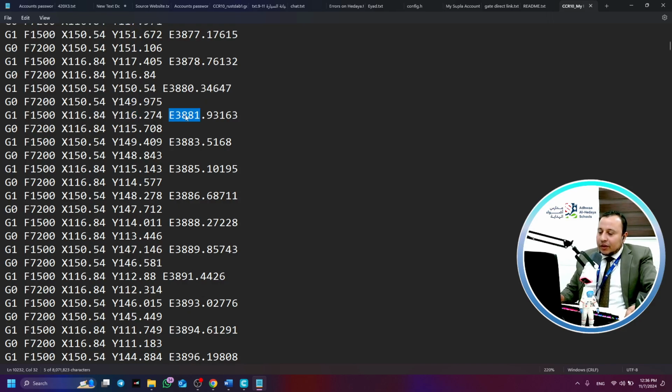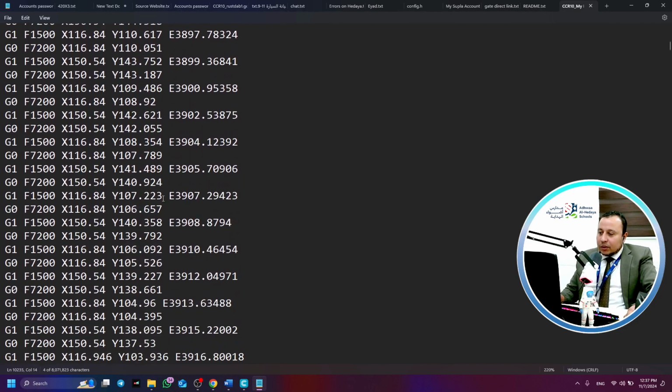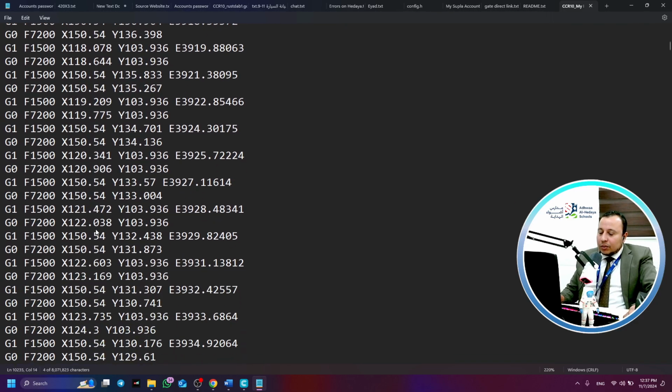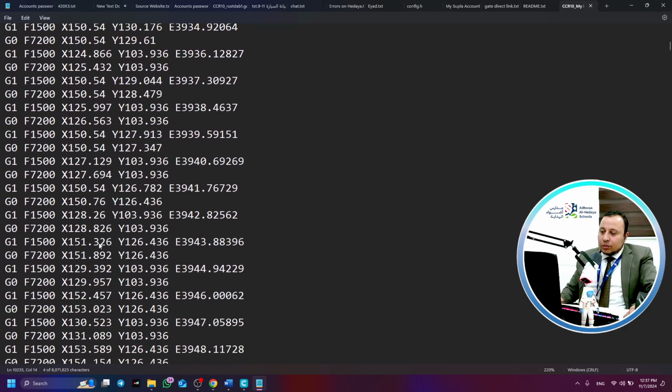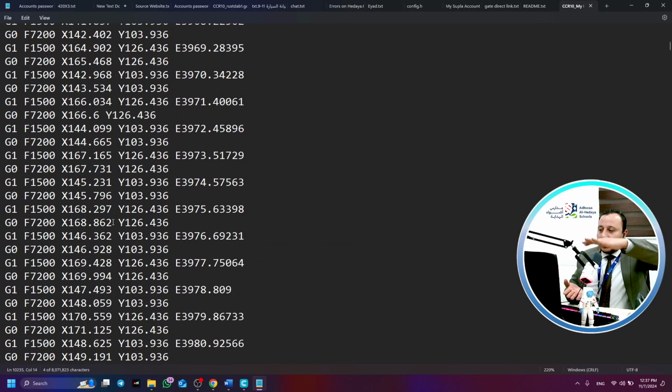You have to push the filament this amount, or move this motor this number of steps, and we also have other instructions for the motors, the X, Y, and Z. Every time you finish a layer, you start the next layer above it. So this is where you order the Z motor to move one step further, so that you will find your model done at the end.